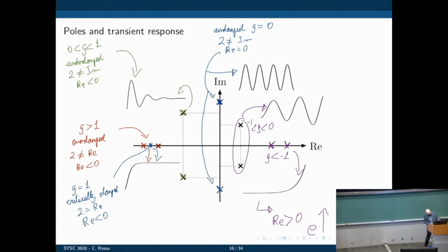Okay, but it doesn't really matter because these systems are unstable. Both are unstable. Both have a positive real part. As a result, exponentials grow to infinity. If there is any sinusoidal component there, that also blows to infinity. Okay, so for a system to settle or for a system to be stable, the real part of the poles, all poles, must be negative. So long as one pole has a positive real part, the entire system blows to infinity, doesn't settle.